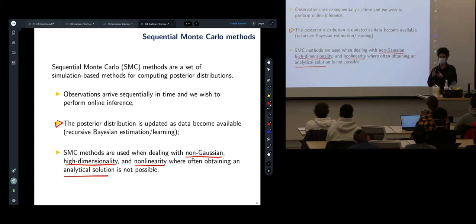So you have two options. You either need to resort to assumptions, right? The model is some sort of assumption because it's imperfect. You're assuming that's the behavior, right? It might be a good model. It can be a good assumption, and that means it works well in practice. Or you need observations, and ideally you need both, which we use both of them in Bayes filtering, right? Now, if you don't have observations and you continue with assumptions and models to propagate for a long time, you might expect at some point, sooner or later, the filter will become degenerate. The amount of information that it's giving you is so low that it's not useful anymore, okay?